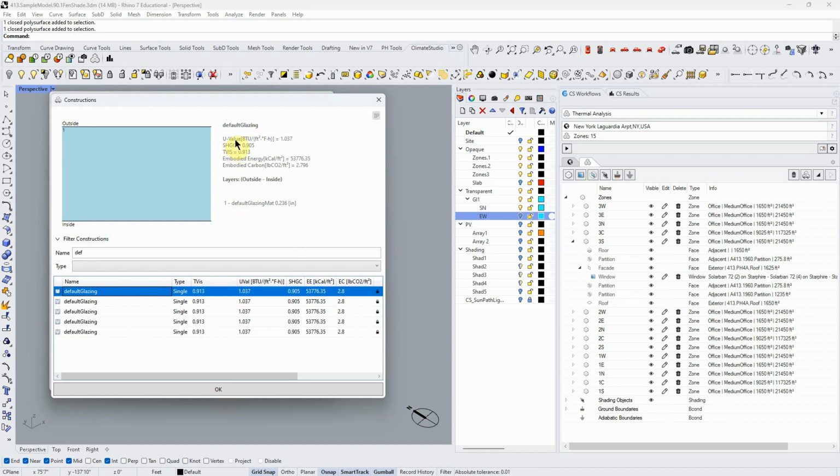Anyway, what are our metrics here? U value, which I already talked about. That is the heat transmittance. It's BTUs, so that's the amount of heat per square foot of surface per degree Fahrenheit per hour, the amount of heat moving through. The reciprocal of that is R value. Usually you use U value for assemblies, and a window is typically an assembly, so that's why we use U value for those. You don't see R value here because windows are never measured in R value, but it's just the reciprocal.